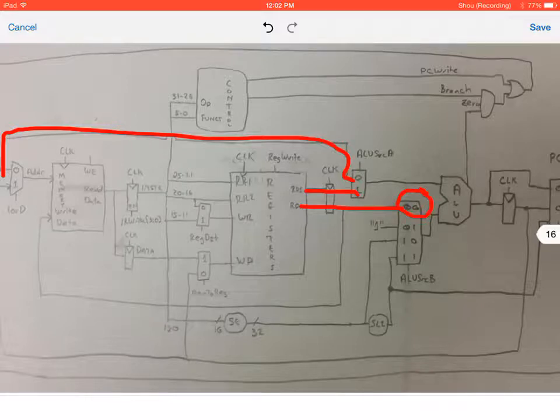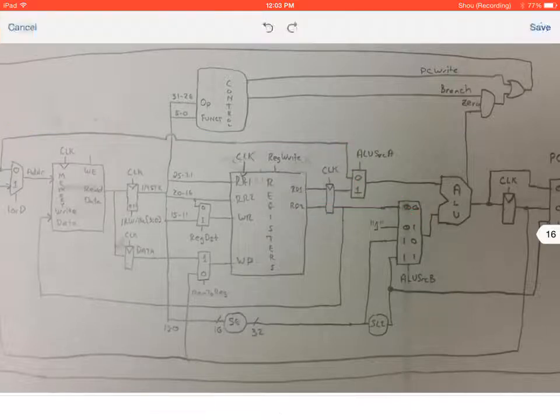1 means we're just incrementing the program counter and using the same ALU, so we're just incrementing by 1. If it's 1, 0, it comes from the sign extended immediate value, which means we are doing an immediate instruction where we're adding the value from the register. So if it's add I, hint, this would be 1 for source A and 1, 0 for source B. And then if it's shift left by 2, that means it's going to be some sort of branch instruction. And we still need to shift left by 2 here because the instructions are still 32 bits.